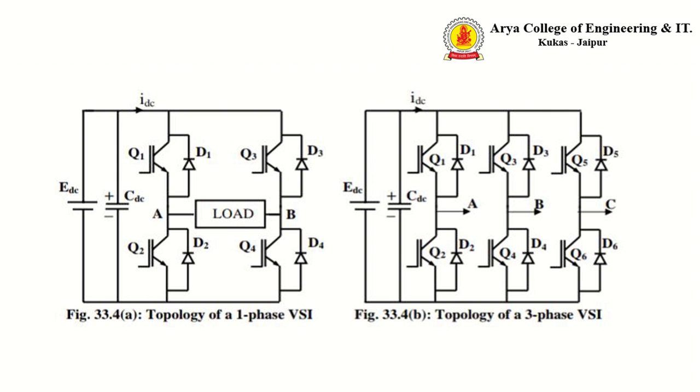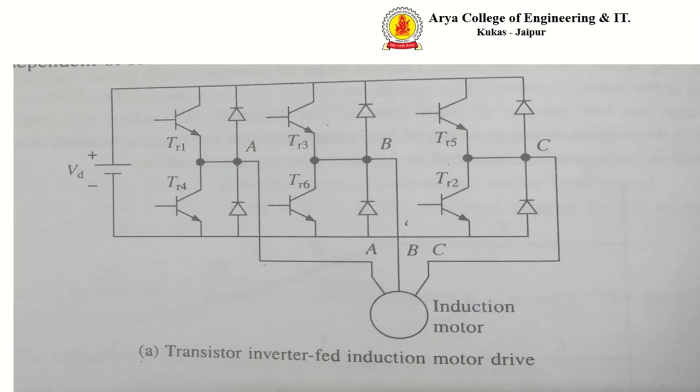And the third drawback: due to harmonics, the motor current increases at low speed. The machine saturates at light load at low speed due to a high V/F ratio. These two effects overheat the machine at low speed. Thus the lower speed is limited to around 40% of base speed. These are the basic drawbacks of voltage source inverter control.